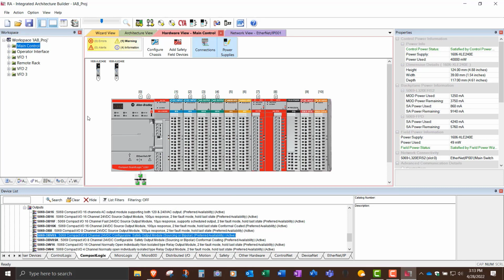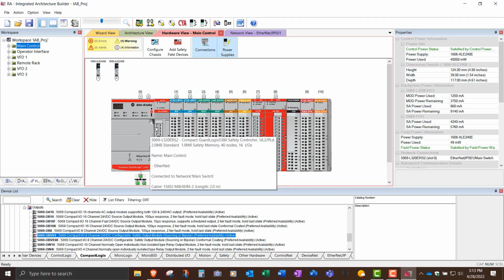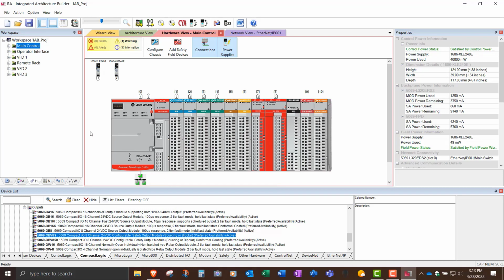Can you use one power supply for everything? The answer is yes. You can run one power supply into both terminal plugs, but again, if you lose that one power supply, you lose any diagnostic capabilities of the controller or the I/O cards by doing that.